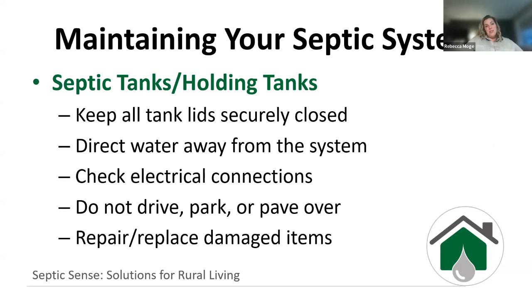Again, the lids, making sure that they're all secured. We talked about overloading or oversaturating the system. So this would be things like directing water away from the system, our downspouts, things like that. We don't want to be adding extra water on top of our system.